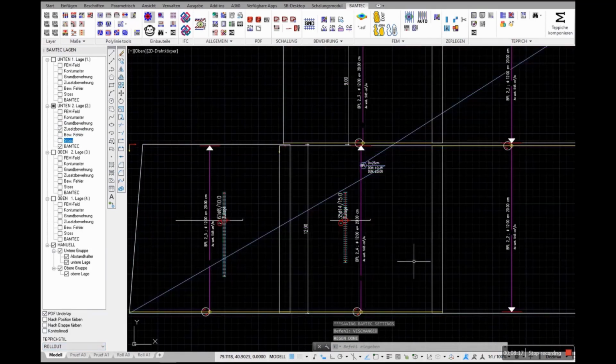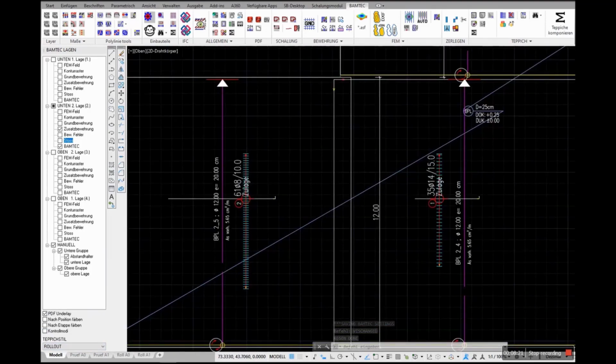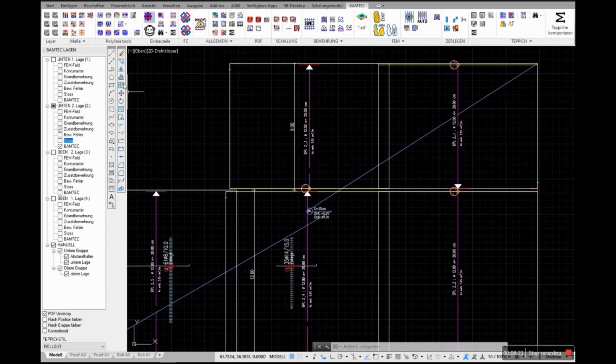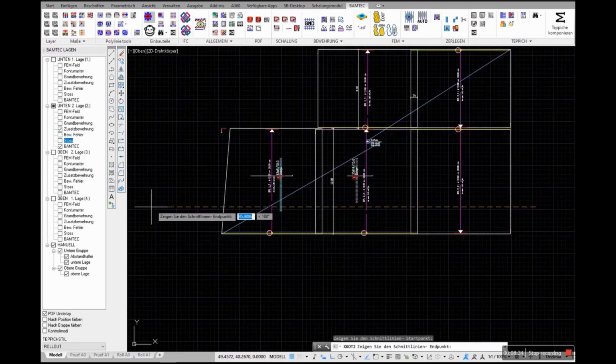Here, once again, a short excursion through the views that are possible. Simple to switch from one view to the next. This is a rollout plan. Now you can only see the carpets with their installation points and the additional reinforcements, easier to dimension, which is also important for the structural engineer, obviously. He wants to see the individual bars, whereas for the users on the construction site, something else might be important.